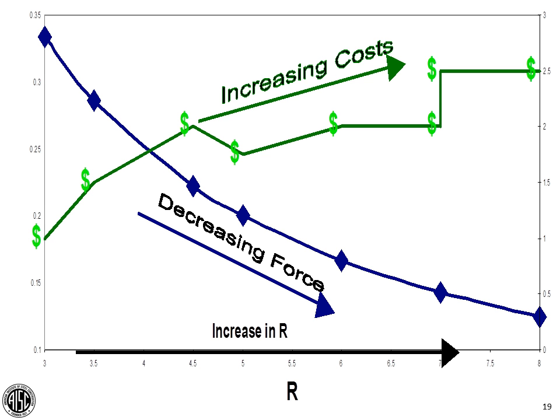When you go to column base plate connections, it talks about if your backing is to the inside of the section, then you can leave the backing and provide that reinforcing fillet. If you're at the top flange of a beam, you're assuming that both those CJP welds are being made from the top of the beam. So at the top flange, you're to the inside of the section. You can leave the backing in place and provide the contouring fillet. If you're on the bottom flange, it's to the outside of the section. So we require you to remove that backing and then either provide another fillet there, or to contour it, or to grind it. And then just a couple other clarifications on this.